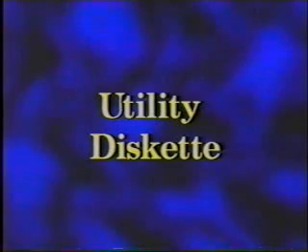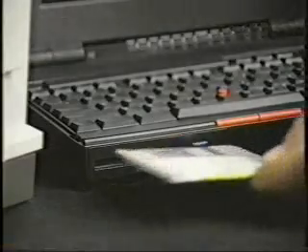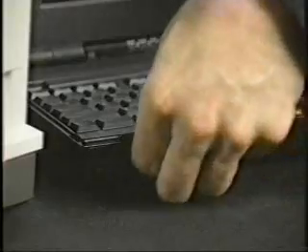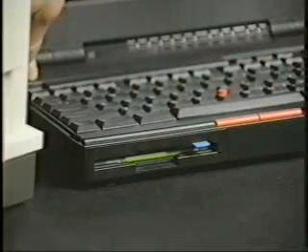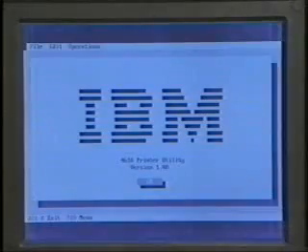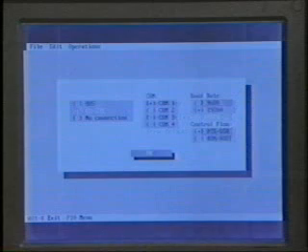The 4610 printer utility diskette is primarily used by CSRs to upgrade the level of firmware. Insert the utilities diskette in the laptop and reboot. At the IBM screen, press Enter. At connection type, select RS-232. At COM, select COM1.